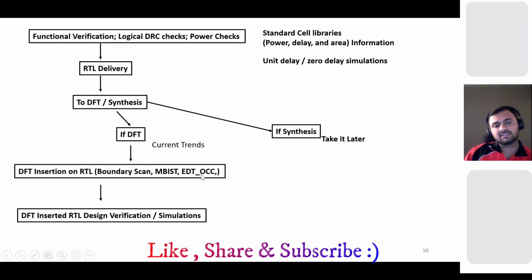And then this EDT OCC. EDT is nothing but embedded deterministic test. It is the compression logic which I showed you. And then you have OCC, the on-chip clock controller. We'll discuss each of them in depth, but just understand the flow and how it works, and then we'll take up each individual one in more detail.